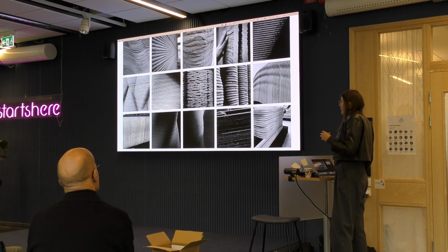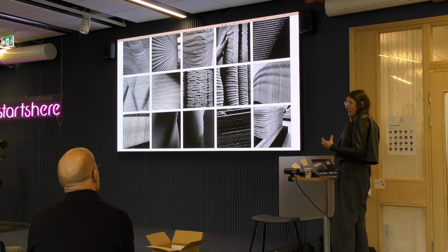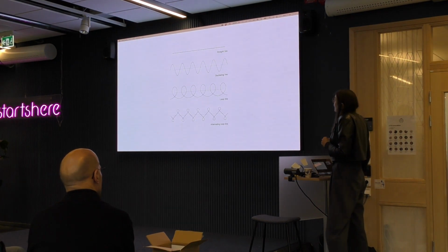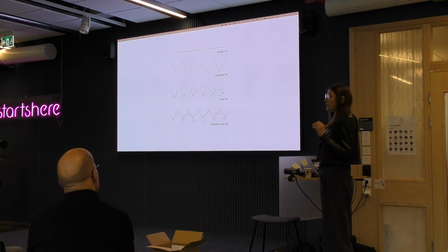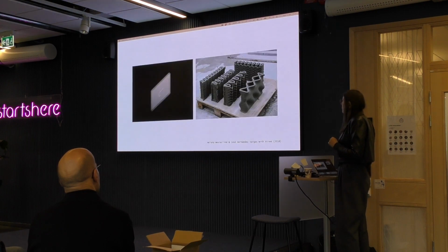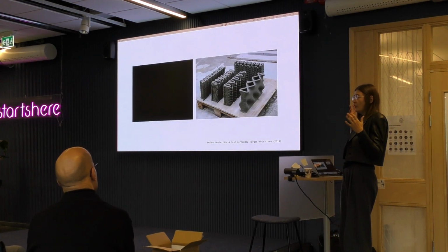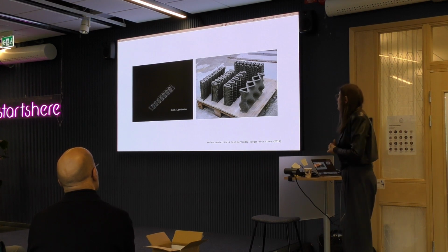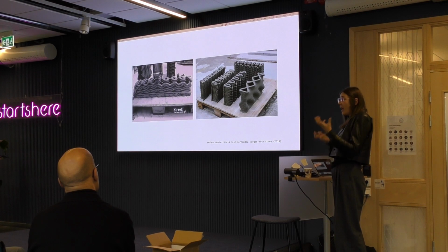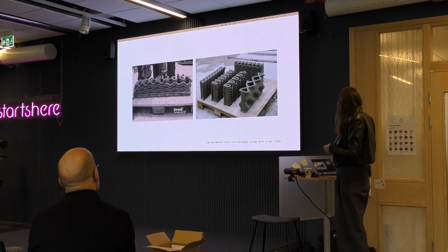So in my doctoral research, this was my starting point. This was a really limited use of the technology, and it didn't really explore its full potential. So what I did is ask what happens if we design the geometry of the line locally. Just by introducing these alternative line paths to the print path, you could create different results. By alternating the layers and stacking them differently, you create perforated effects and inbuilt cavities in the concrete that we thought had a lot of potential.